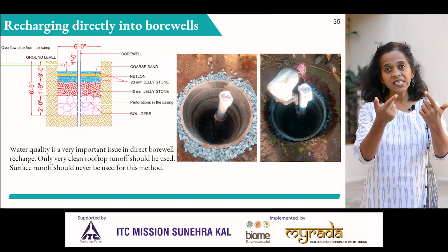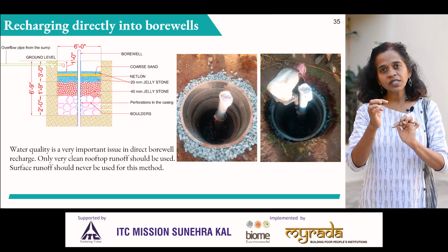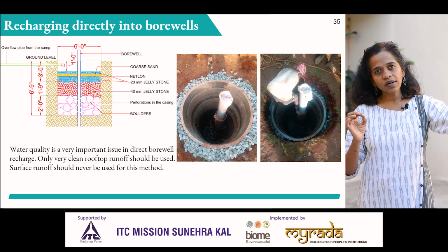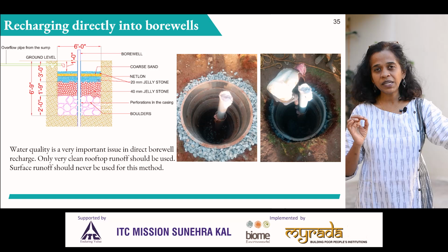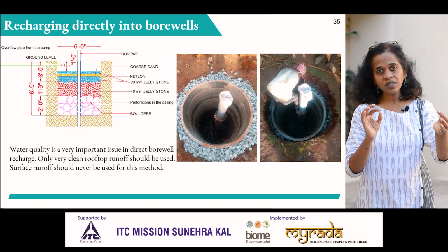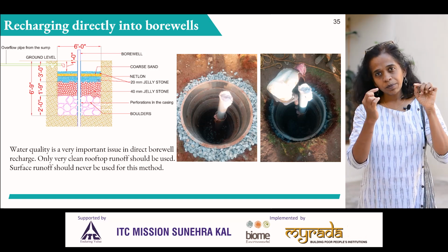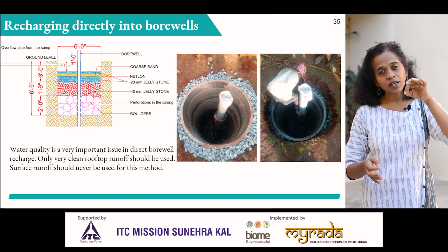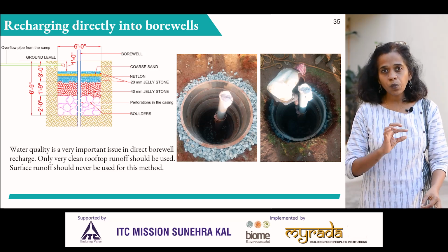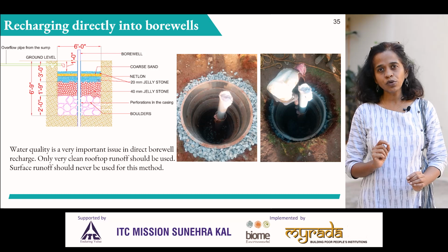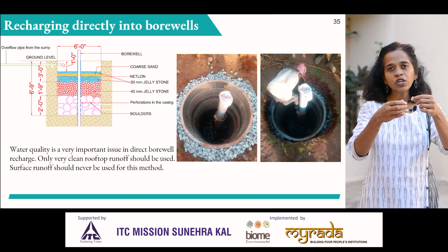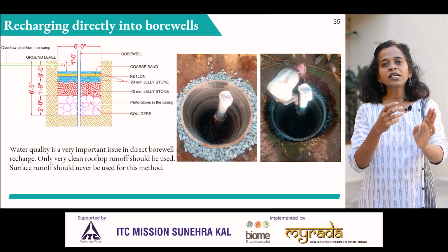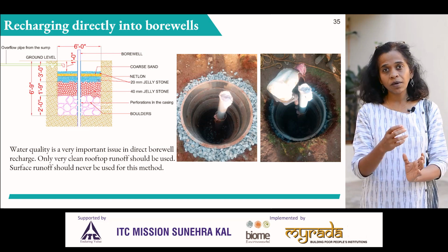The borewell casing, we make perforations in the borewell casing so that the water, once it comes through the channel, falls into this pit, filters through these stones, goes through these perforations in the borewell casing to the deep aquifers from where this borewell used to be able to draw water. Some of the things to keep in mind: when you make perforations in the borewell casing, make sure that you wrap it with Netlon mesh.